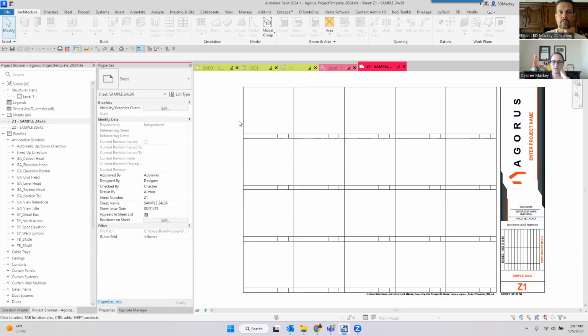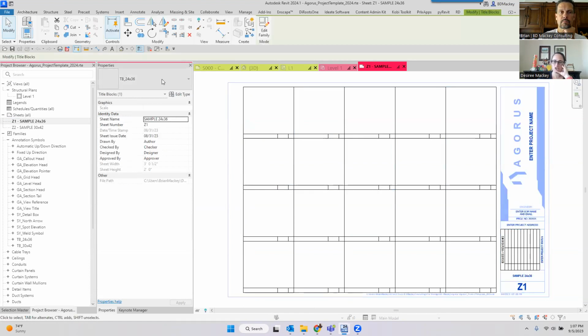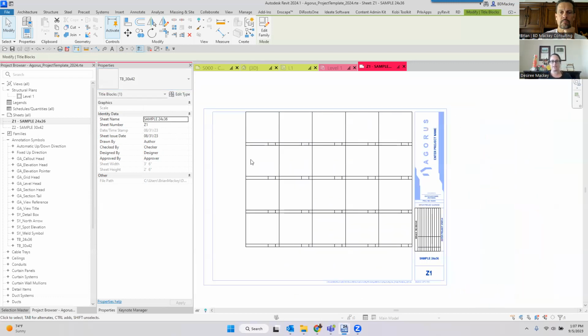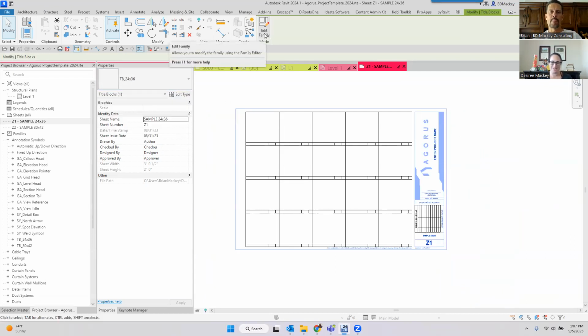And one of the things we were discussing was sheet sizes, because for the most part we're a smaller sheet size, but occasionally there's a bigger one. And I want to preload a lot of typical details in the template and things like that. So I don't want the detail locations to move around if they're just changing sheet size. I don't want them to have to touch every typical detail and nudge it around if the detail boxes get slightly different. So I managed to sort it out that I just have the insertion point of the title block being the top corner,